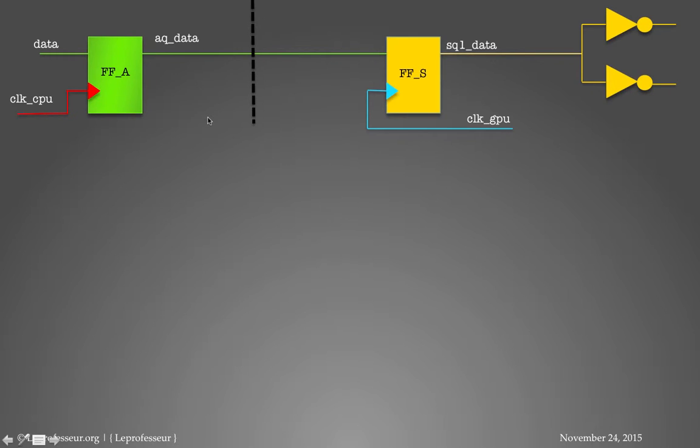As the name stands out, clock domain crossing. So we're going to cross some signals from one clock domain to another clock domain. And these two clocks are not synchronous, they are asynchronous clocks with different frequencies. So for example, in this diagram, we have the CPU clock domain and the GPU clock domain, and we are just passing one signal. Now, here in this diagram, we have just one flip-flop, a synchronizing flip-flop in the receiving clock domain. Now, this is a typical example of clock domain crossing.